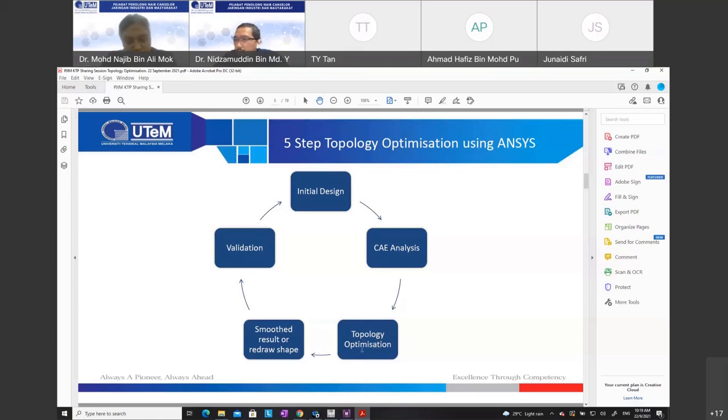You do the topology optimization. Normally in topology optimization, there are certain constraints. For example, a constraint can be to optimize based on natural frequency. Another constraint is based on the strain energy of your structure, I mean, based on your deformation. For example, at the same deformation, you want to optimize the structure, or based on the stress of your structure, you want to optimize the topology.